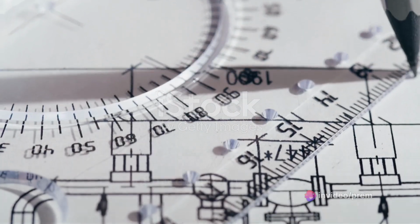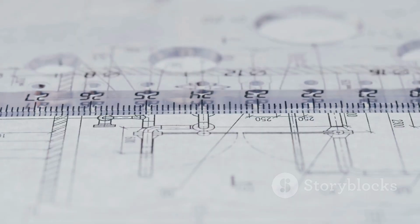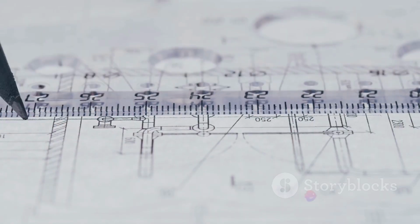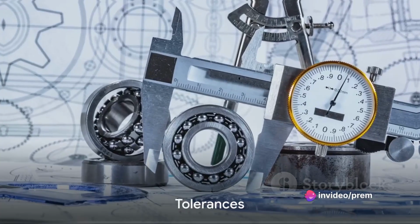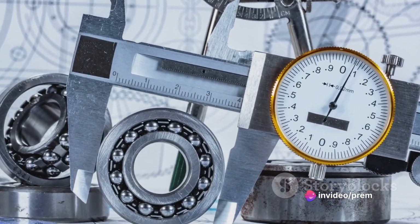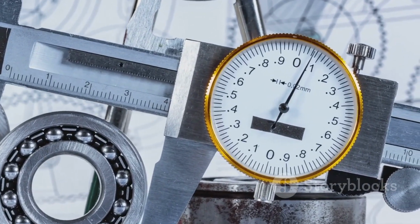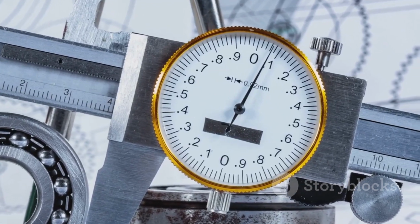Dimension lines show the extent of a dimension. Arrows indicate the direction and extent of the dimension, and numerical values provide specific measurements. Tolerances form the 7th step. Tolerance notations indicate the acceptable variation from the specified dimensions, while geometric tolerances specify allowable variations in form, profile, orientation, and location.